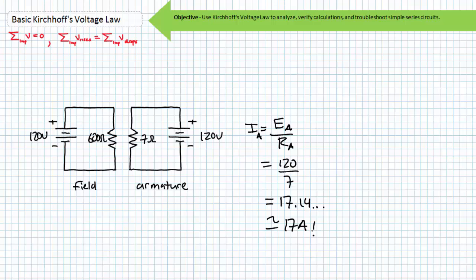A locked rotor condition, one in which the motor shaft isn't spinning due to application of too much load torque, is clearly something to be avoided for any considerable length of time because of such a large current draw. However, a spinning armature exhibits another phenomenon known as counter-electromotive force, sometimes known as CEMF, due to the generating aspects of moving a conductor through a magnetic field.